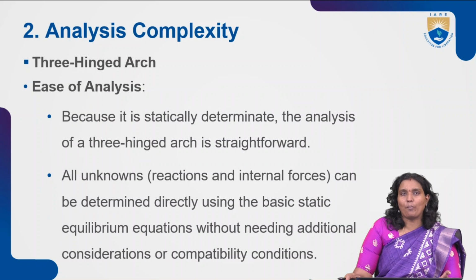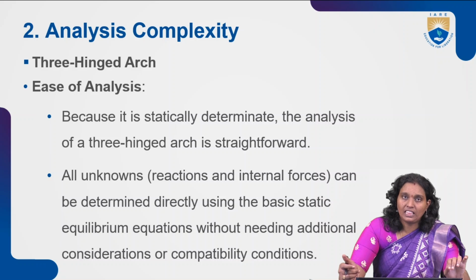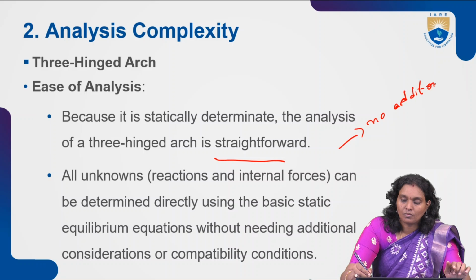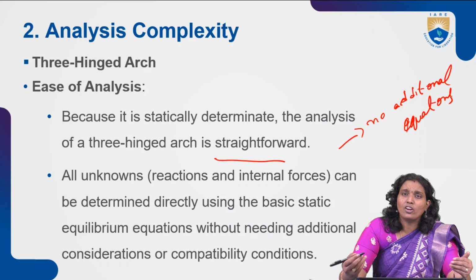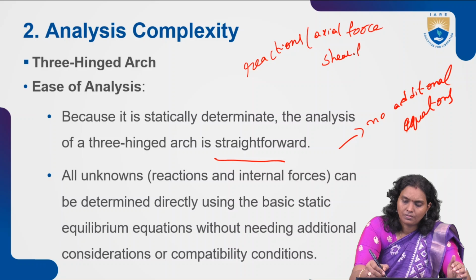Coming to the analysis complexity. In three-hinged arches there is ease of analysis because it is statically determinate. The analysis of a three-hinged arch is straightforward. No additional equations are required. All the unknowns, those are reactions: axial force, shear force, bending moment.